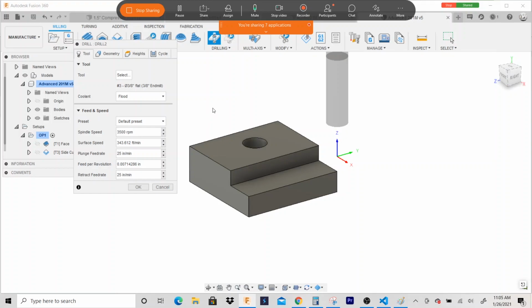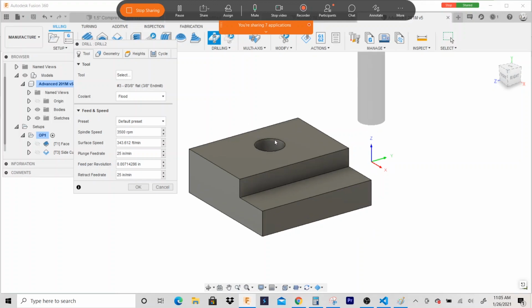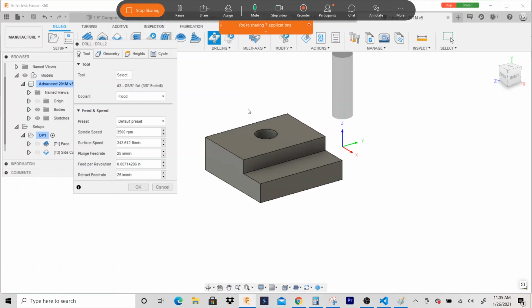They usually go in simple fractional increments. You know, like 27/64s. A machine shop will probably have that drill size, but the school, there's a good chance they won't. They're probably gonna have like the basics. So the size smaller from .42, like the basic size that's most readily available, is a 3/8 drill.